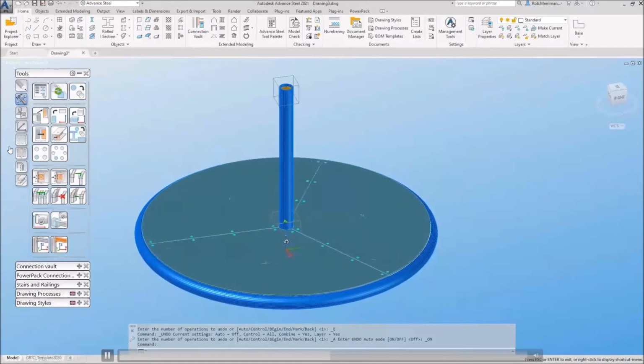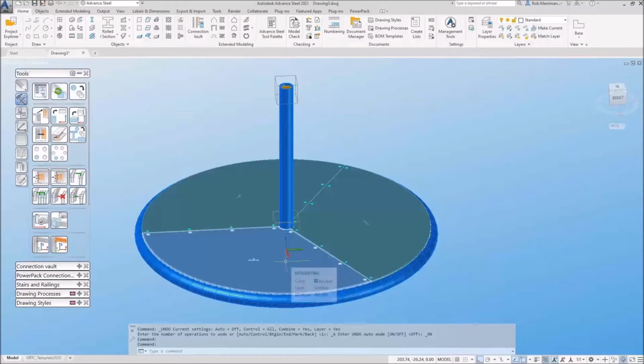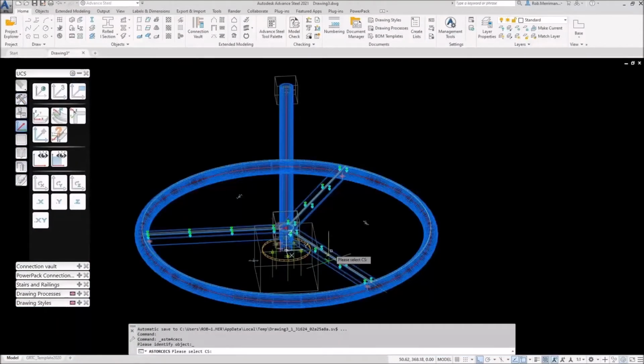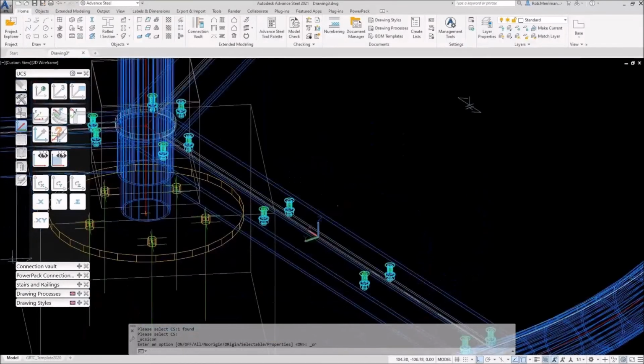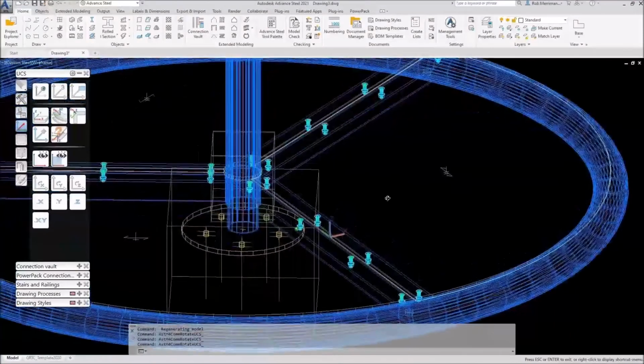Now, what we're going to do next is actually put the roundabout in the park that I take my kids to. It's got some little motorbikes on it, so we're going to create a couple of little motorbikes, and then the handles here. Okay, so for the little motorbikes, it's going to be fairly straightforward. What we're going to do, we're going to use the UCS object, but this time on the little T sections, because I do actually want it in the middle of the T. So we're just going to rotate round, so our XY is pointing that way.